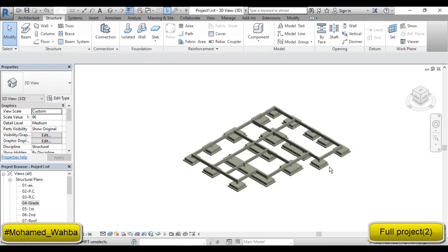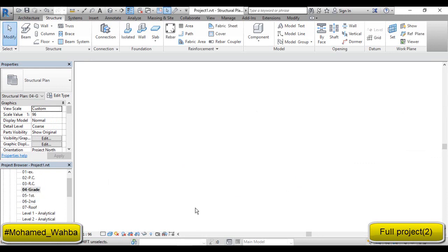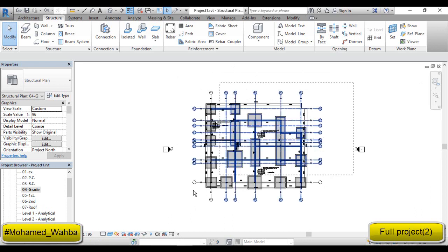We have to continue. We need to draw the columns above those beams, to extend those columns to reach the other levels here in my structure. So I will choose here. We can do that easily. When we choose the grid beam level, I need only to select all the columns in this selection to copy or replicate them to other levels.